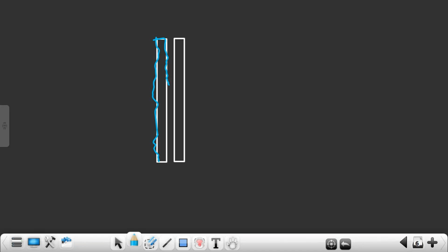If we see in centimeter scale, it is planar, but in nanoscale, it's not planar. It is like this. So without our knowledge, both of these metal layers are shorting here. This type of problem may happen in an IC, but we are not aware. When both are shorting, the chip will not work properly. Obviously, there is a defect in the chip.